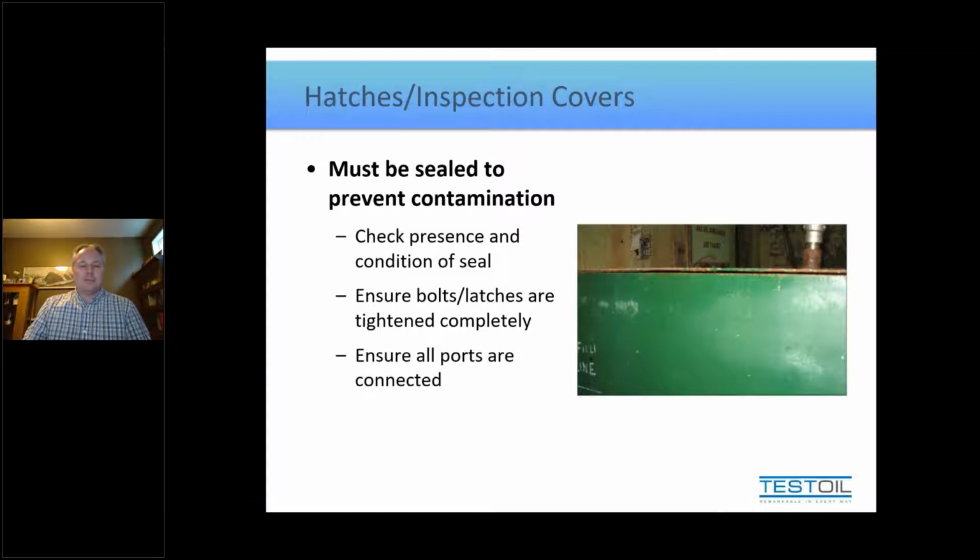So many times I've seen breathers installed in such a way that there's somewhere else the air will breathe. So it could be those quarter turn breathers are left installed. It could be that there's more than one point of entry into the tank, right? And they haven't all been plugged up. And more times than not, it's because seals have either been compromised, thrown away, damaged, whatever it is. And if we don't have the system completely sealed in every other spot, air will not breathe through the breather. So simply installing one doesn't actually get you all of the effects you're hoping for.